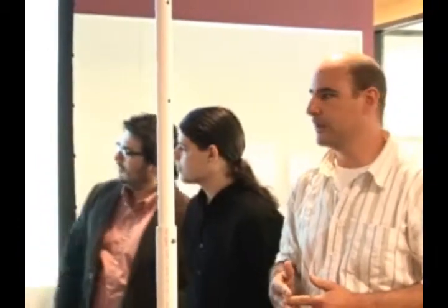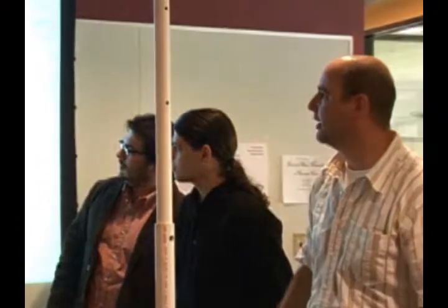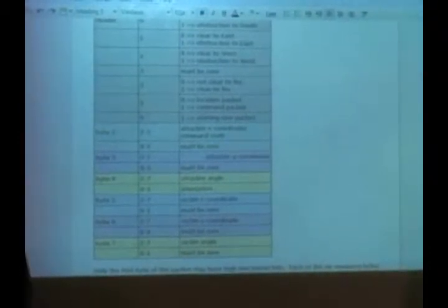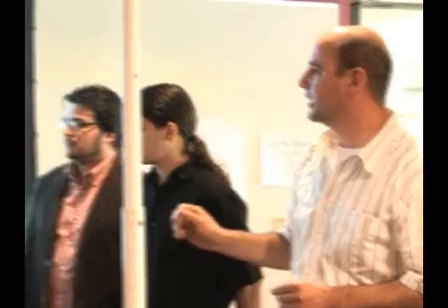So that's the communications protocol in a nutshell, and we have a little diagram on our poster, up on the screen here, that describes what each field is. You can see the gray portion is the metadata part, and it also contains bits that describe obstructions and whether or not the robot has a clear shot at the target. We ended up not using that information in the end. It was a fallback in case we couldn't get infrared working reliably. We think we have that worked out pretty well, so that's there, but we're not currently using it. And then the colored parts on the bottom are the data payload.